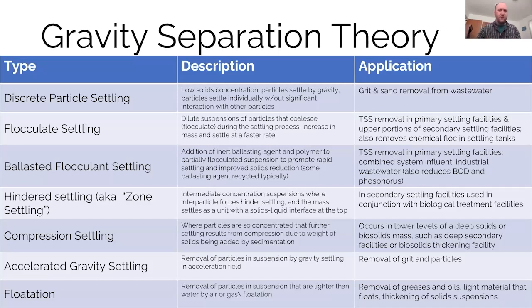Compression settling, that is what I was talking about with that gravity thickener, is the main principle behind that. But of course that happens in clarifiers in general at the bottom. That is when the sediment itself is pushing itself and squeezing.